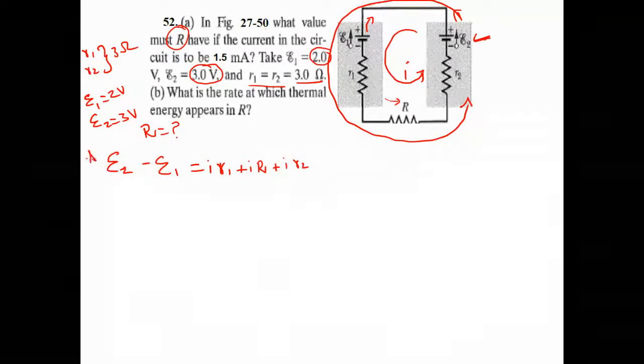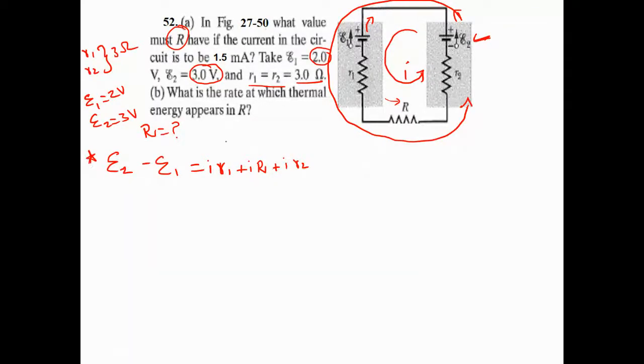So I'm going to use this equation. First of all, I have to rearrange this equation. How to rearrange, my dear? I'm going to separate the battery, because we already separated. So now we take the current as the common term. So here the current is very common. I times (r1 plus capital R plus small r2), and on the left hand side E2 minus E1. Am I right or not? Yes.